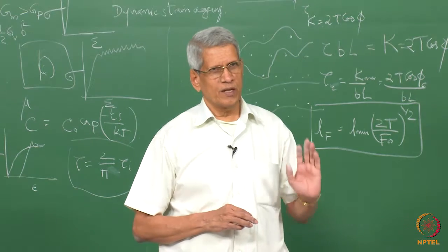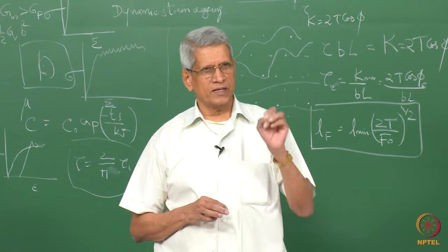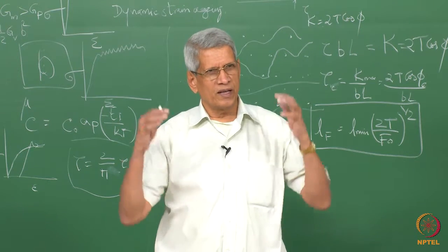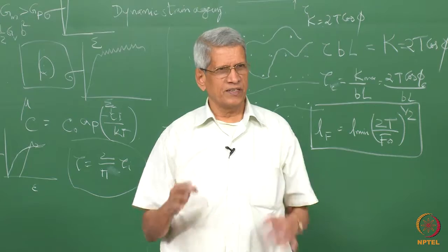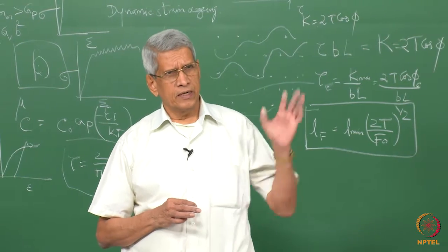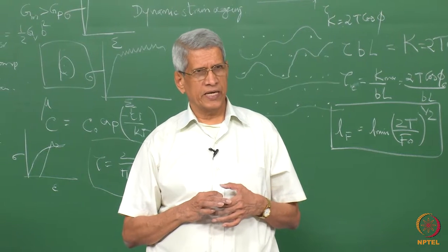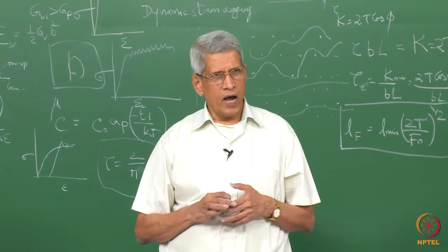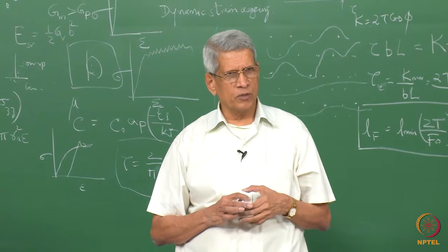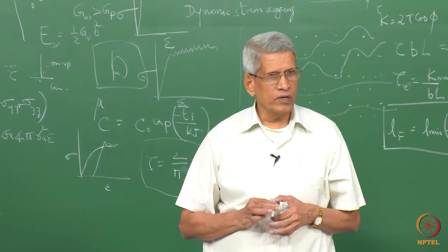So with the coherency strain, the dislocation can interact, and depending upon the sign of the strain, positive or negative, it can be an attractive or a repulsive interaction. That also has an effect on the critical stress which is necessary for the dislocation to overcome the particle. Stacking fault energy in the matrix and in the precipitate could be different. Then if there is a variation in stacking fault energy, that much energy difference may also be necessary. The force necessary to generate that stacking fault energy also has to be provided for the dislocation to pass through it. Correct?